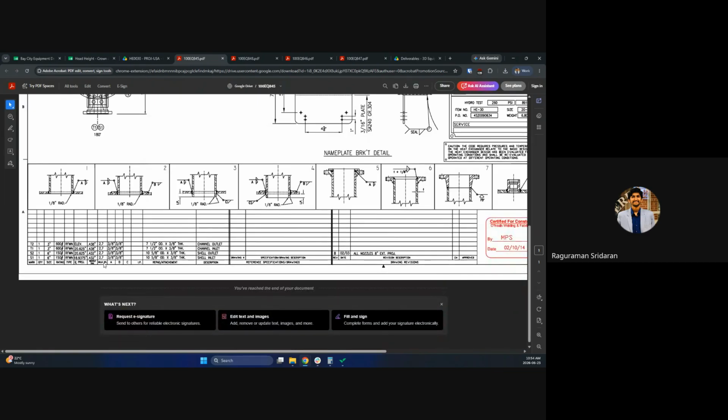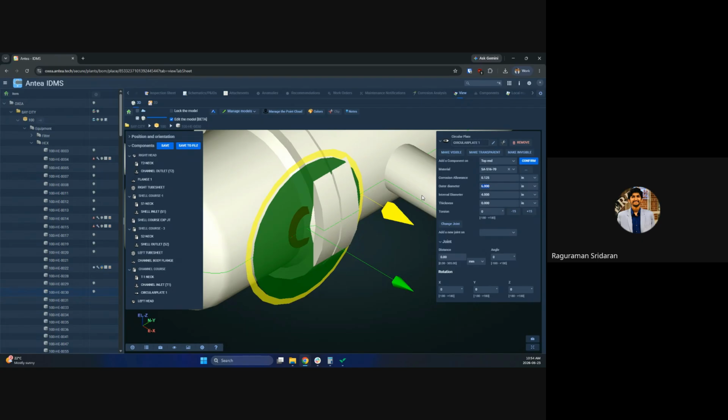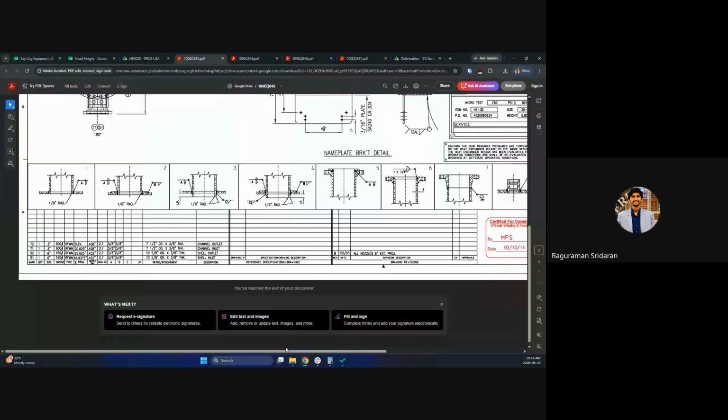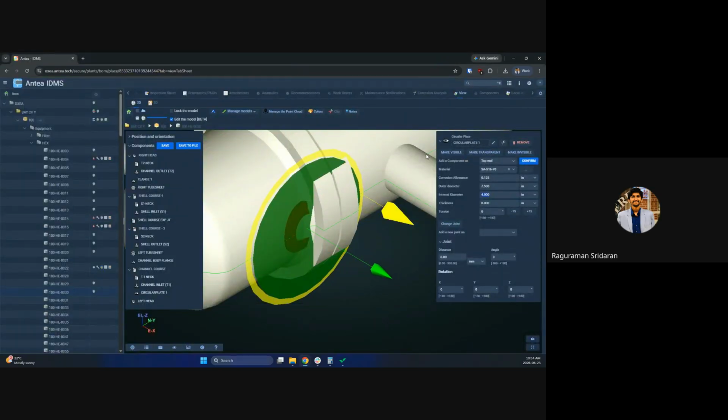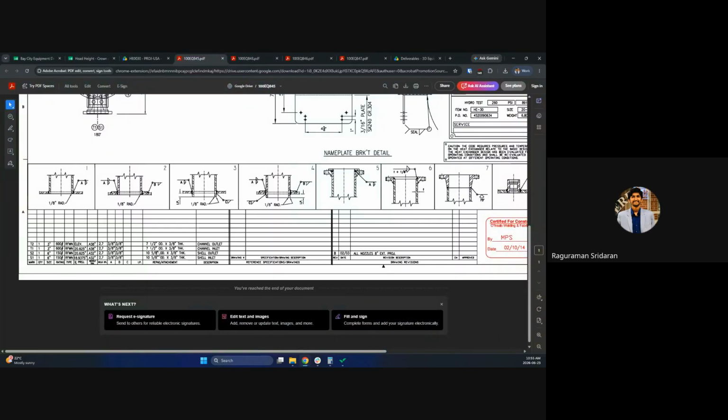It's there. Here, I guess they are providing this information about the repad. So we are looking for T1, I guess 7.5. 1.5, and I guess the internal diameter is going to be 3 point something. Let's see. 3.625, and the thickness 3/8.